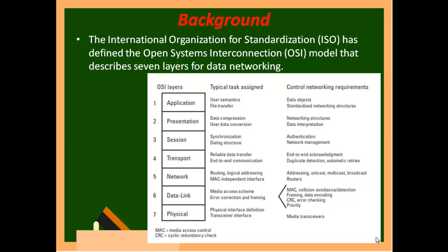So you see that small red cross mark in the image. Once you refresh, it may get the data and show you. If it is not received, CRC, cyclic redundancy check, fails, so it will automatically refresh and try to get the data back.